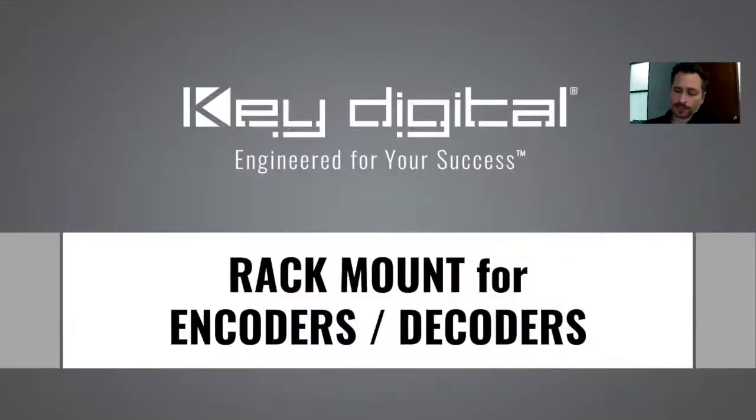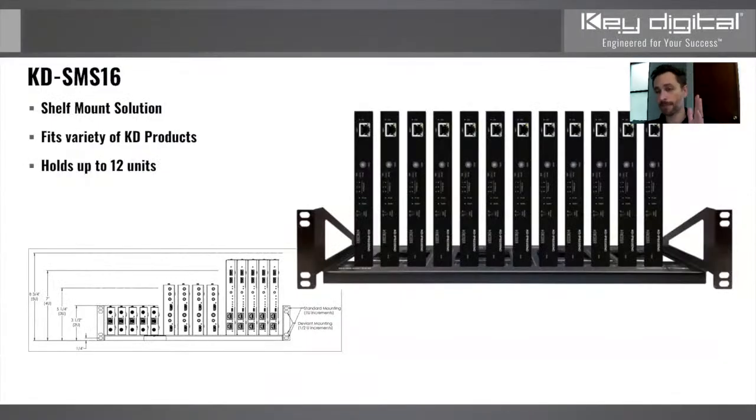Now with these products, we have a special shelf mounting solution, KD-SMS16. Although the number 16 is in the model number, you can only fit a maximum of 12 of these units on the shelf. That's because you must keep your ventilation. Do not put metal to metal contact here.